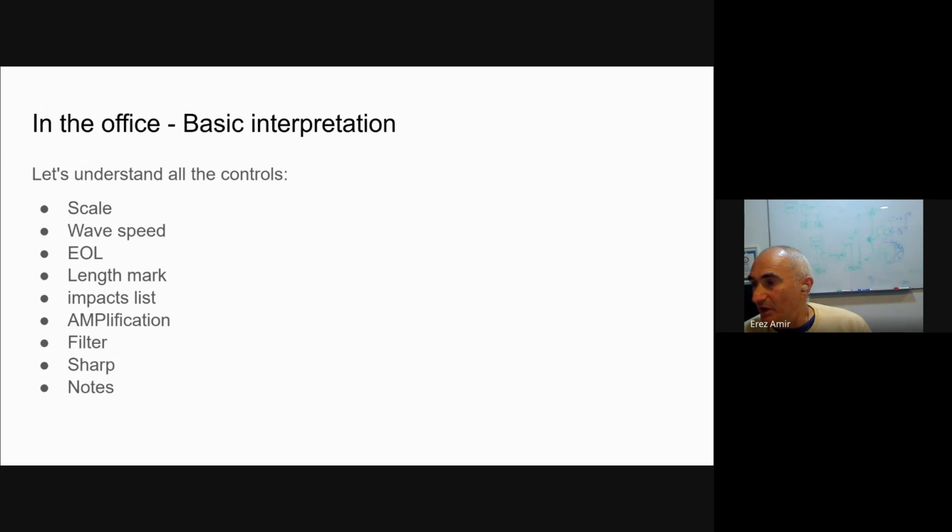Okay, I saw here a question from Carlos. What should be the initial position of both friction and amplification to start up with? Okay, so friction, in real life, is not something that we can control. The soil creates the friction. The higher the SPT N value, or the stiffer the soil, the more friction we have.